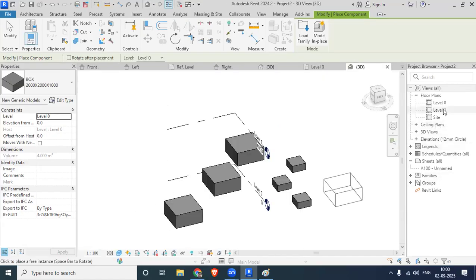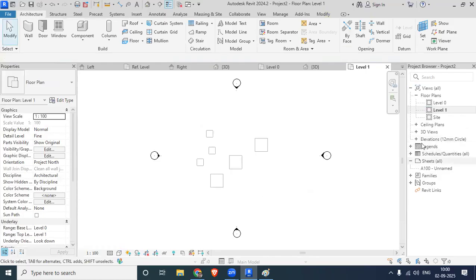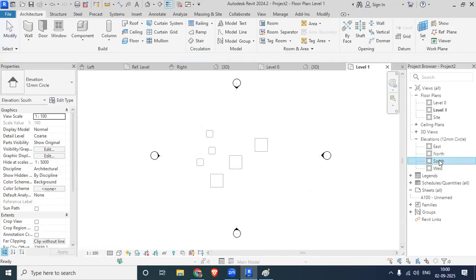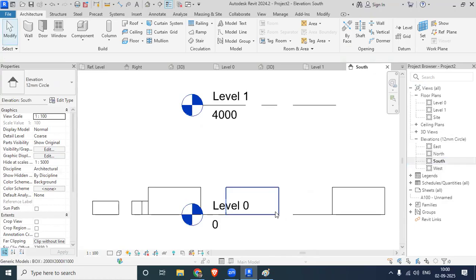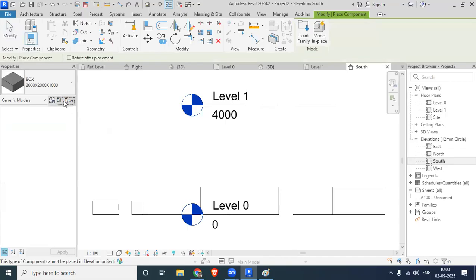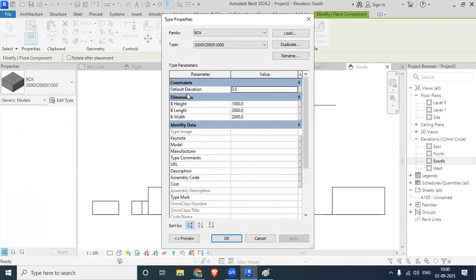And all these will be at the reference plane. Let's go for one elevation at the reference plane. And you might have noticed that there was already a parameter there saying height from reference. Let me see if I can utilize it. Where is that? This one. All right.